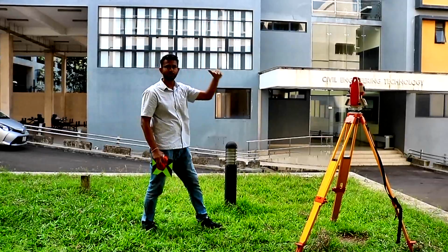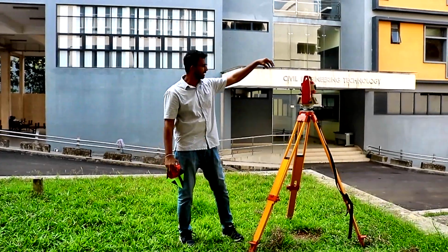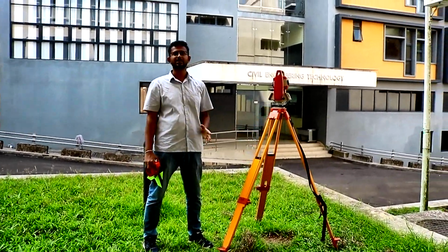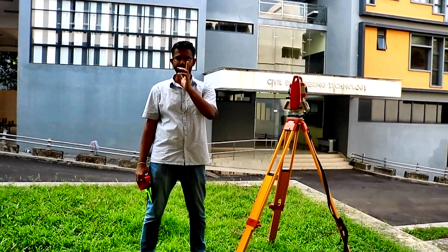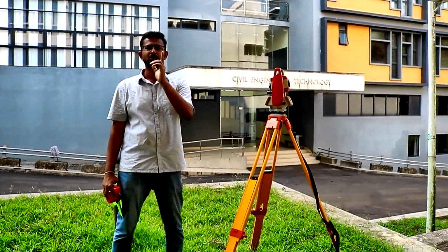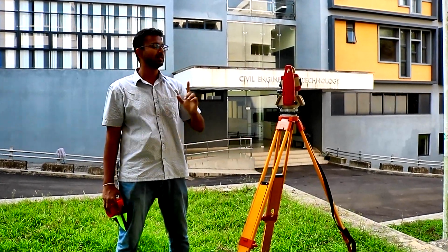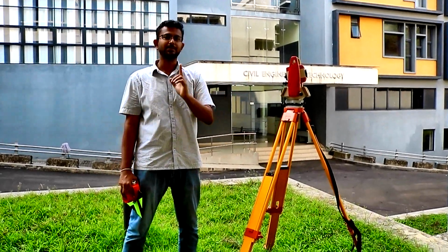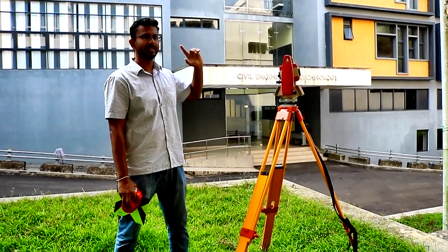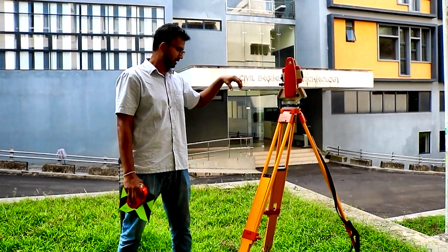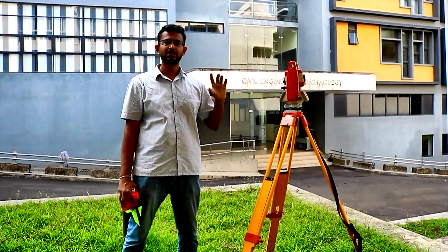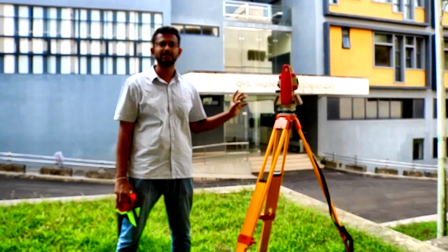Similarly, for the total station, also we can feed its location and the direction. That is one method of doing the orientation. So that is called the Backsight Azimuth. There are 3 methods of doing the orientation. The first thing is Backsight Azimuth. The second one is the Backsight NEZ. So we are giving 2 coordinates to the instrument. So that is called Backsight NEZ.